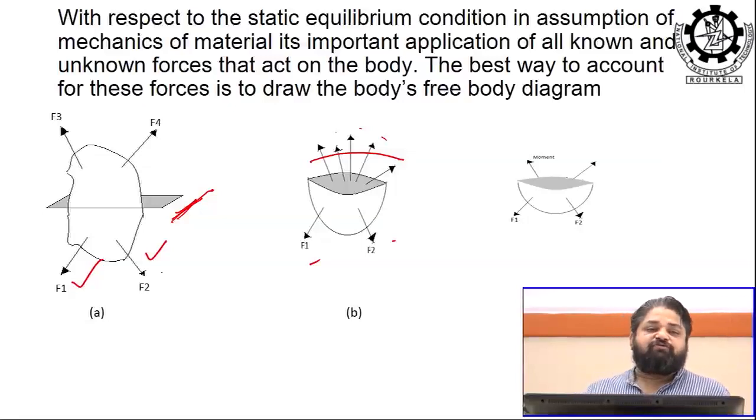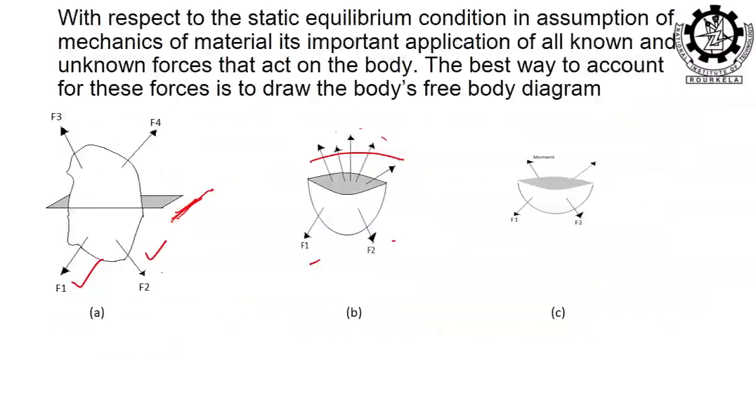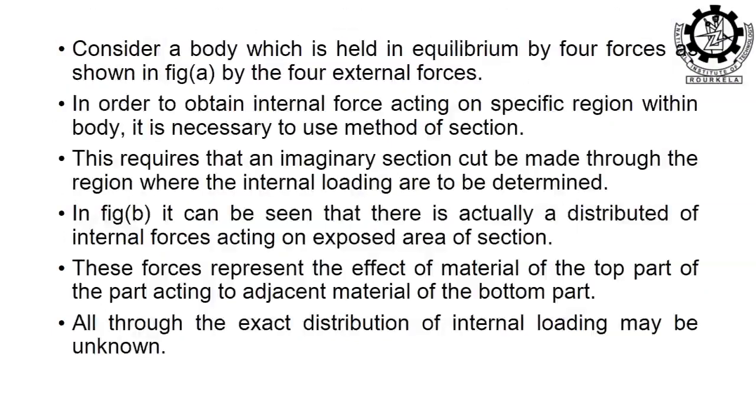The best way to account for these forces is to draw the free body diagram. The same thing I discussed earlier is said here. Consider a body held in equilibrium by 4 external forces, shown in figure A. In order to obtain the internal forces acting on a specific region, it is necessary to use the method of sections, which requires that an imaginary section cut be made through the region where the internal loading has to be determined. Figure B shows the cutting and the internal forces coming out.